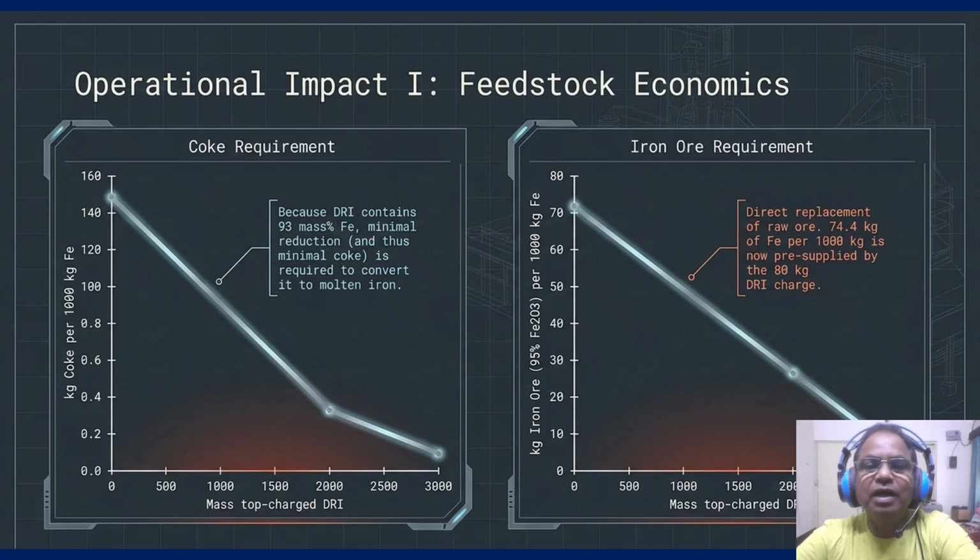But look at the operational bonus on the bottom. Less coke consumption means significantly less blast air and therefore less nitrogen is forced through the tuyere. This reduces the top gas volume. Now the question arises, why is this and what is the so what factor?